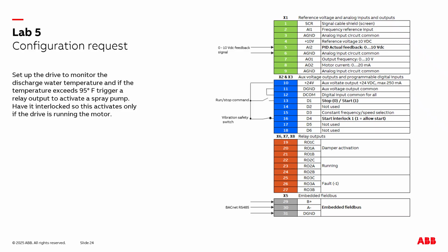Just because the temperature in the pipe or the water may be 95 degrees Fahrenheit or hotter, we don't want the spray pump activating if the drive's not running the motor. So we have to have two conditions: the drive's running the motor and the temperature exceeds 95 degrees Fahrenheit.